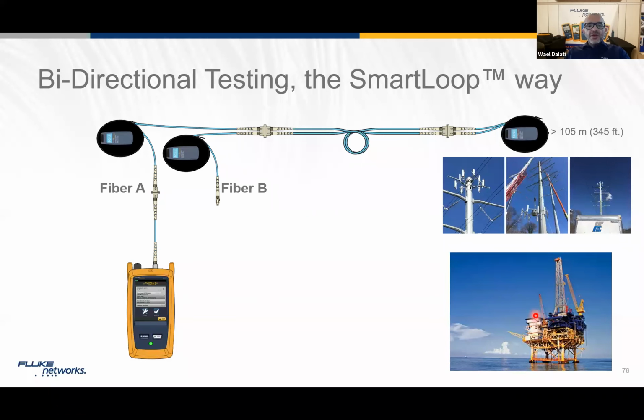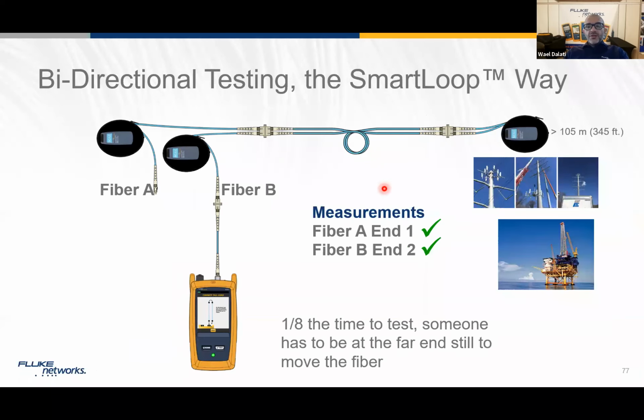And that means that what we're doing now, we start our test in fiber from one direction. So I shoot my light inside fiber A. It goes in fiber A, goes into the drum, goes back to fiber B and goes out from here. So I test one direction of that cable. That means I now move the OTDR to the second cable. As you see, I'm still in the telecom room. I did not change anything on that side, on the side of the middle drum.